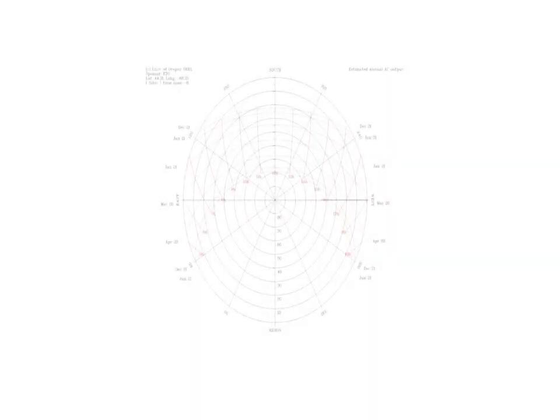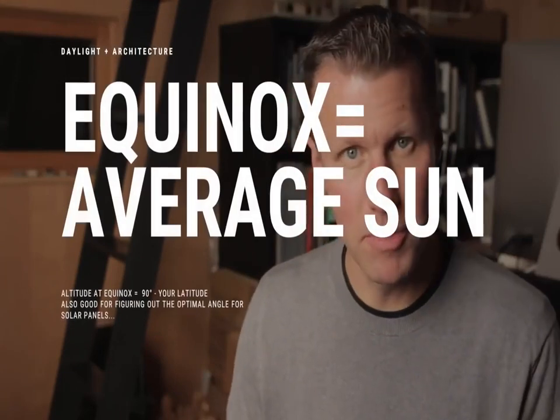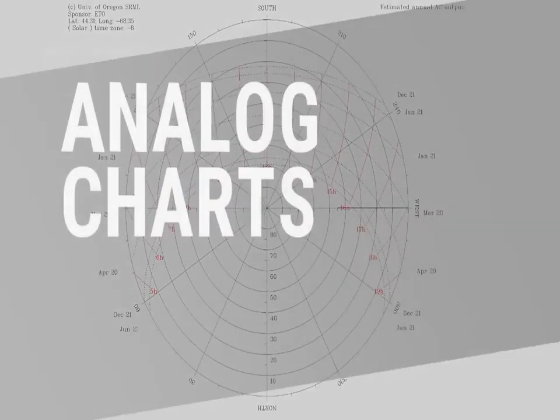Now, a lot of people have been asking about these, and I'll quickly show you how they work. There are essentially 4 dates in the calendar year that you care about when considering the sun's impact on your architecture. The solstices in December and June are the points when the sun is at its extreme arc, either high or low. And then there's the equinoxes in March and September. These are the midway sort of transition points between the two extremes. To design the depth and spacing of the louver blades, you'll want to know the altitude of the sun at solar noon for each of the 4 important dates.